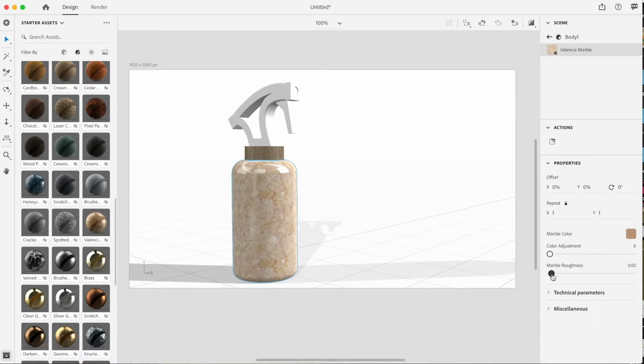In real life, nothing is 100% reflective. Maybe some shiny black colors, but with studio lights. But in real life, when you're photographing something, it will never reflect 100% sharp reflections. So we will add a little bit of roughness. Let's say 10. Okay, this is too much. Sorry, I thought it was by 100. It's not. So it needs to be 0.1, maybe a little more. It's still pretty strong. Okay, let's say 0.5, 0.3, maybe. Okay, let's stick with this. Let's set it to 0.4.